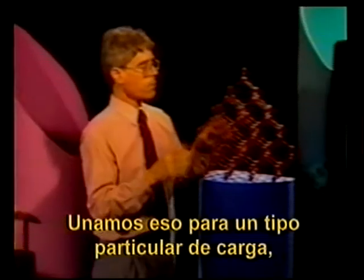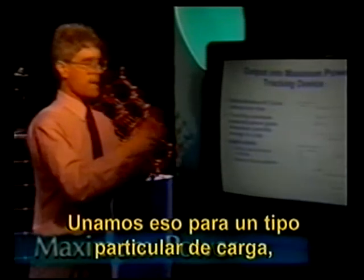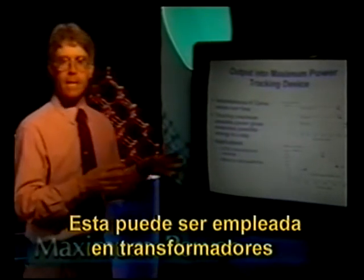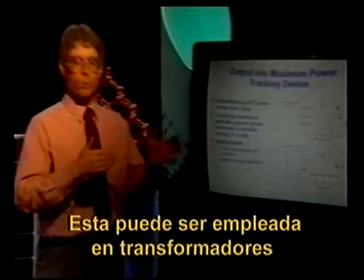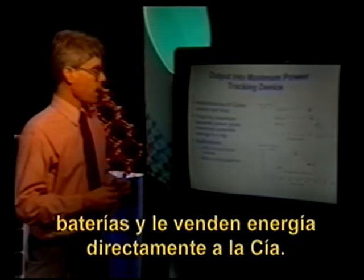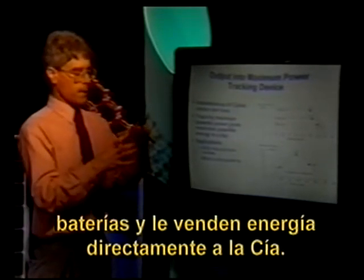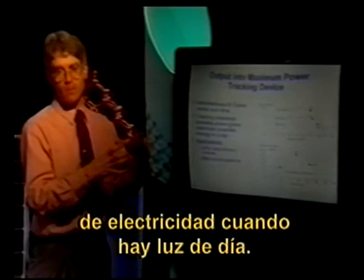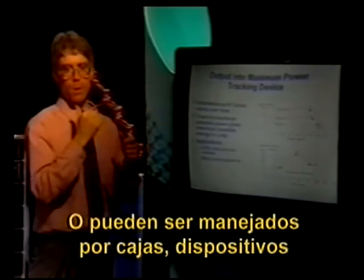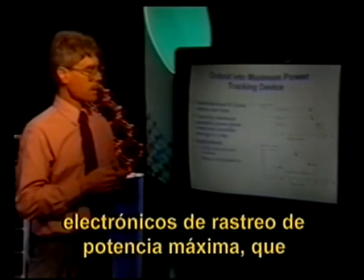Let's put that together for a particular type of load, the maximum power tracking type of load. This might be used in utility interconnected inverters, the type that don't use batteries and sell power directly to the utility during daylight. Or they might be driven by electronic max power tracking boxes, devices that make a good match between modules and motors.